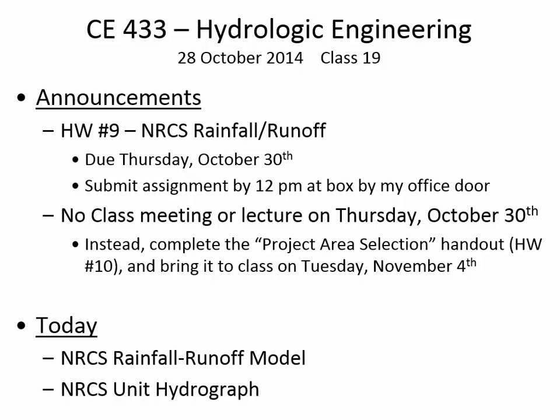And so steps 1 through 5 is just a way of you estimating the area of the watershed, gathering some land use information and soil type information. And it just relies on using Google Earth, which you can install for free, and I think is already installed on these lab computers out here. Using aerial photos to look at what's there and estimate what the land cover is. You know, is your watershed 100% asphalt area, or is your watershed scrub oak, and so on. And then also collecting some of the soil type data for that area in the same way that you will for this week's assignment.